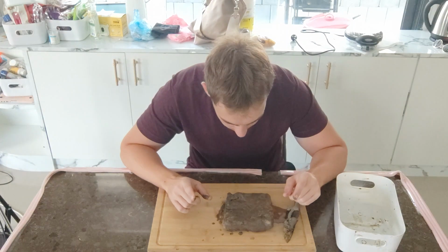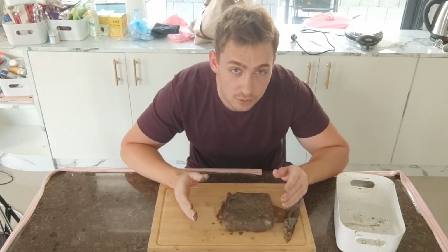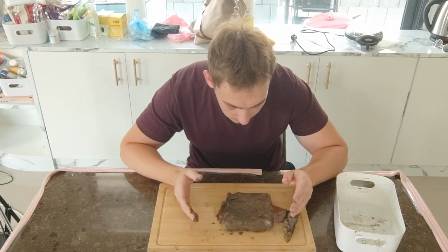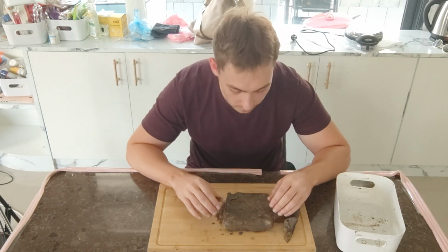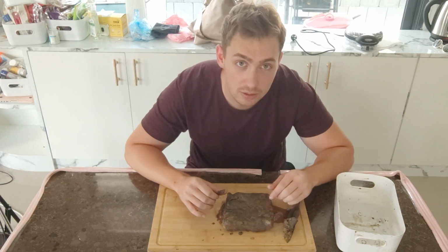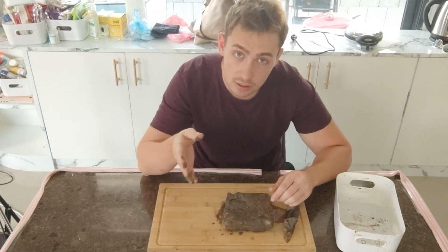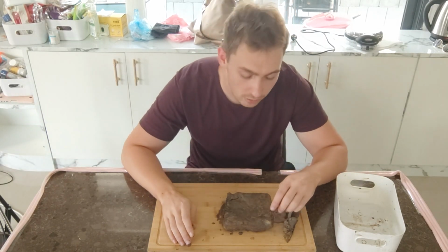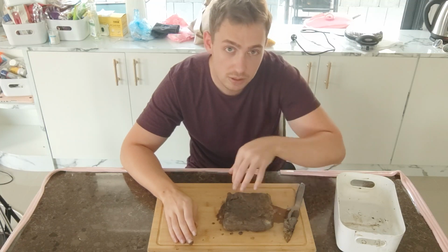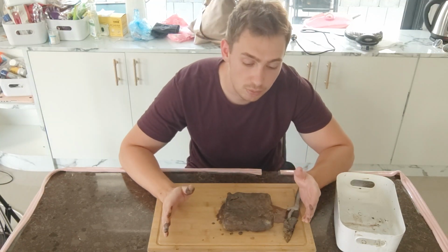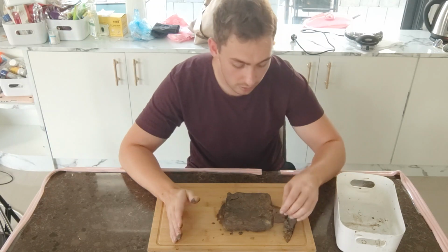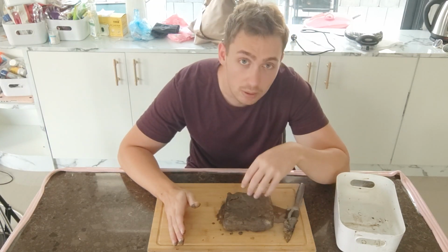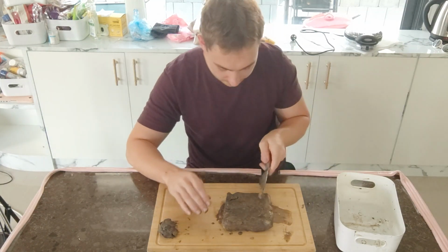So here is what we're going to do. I'm going to try to make it as square as possible to visualize once it's milled, and then I'm going to make some different kinds of placements and cuts in it, depth cuts, and then I'm going to draw it in Inventor, and we're going to talk about where we should start with the 0 point or the dimensions, where they should be placed, so it's easiest for the machinist to set them up and measure it and put out the 0 coordinate for his coordinate system in the machine and mill it. Okay, so I'll cut it.